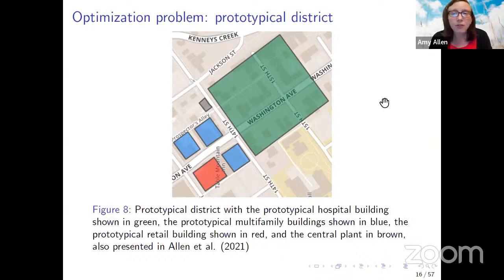And these data-driven meta models then provided a computationally efficient way of predicting building thermal loads as a function of network temperatures in the ambient loop. And these could be readily integrated with a model of the district thermal energy system created in Modelica, which I extended from a model originally created by Eustace van Rijn, another student who worked in Professor Hens's group.